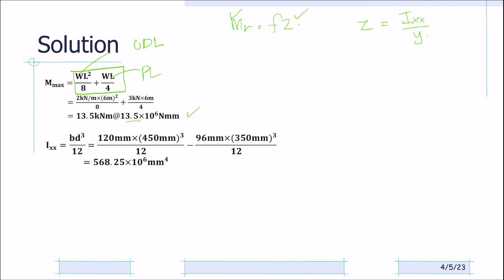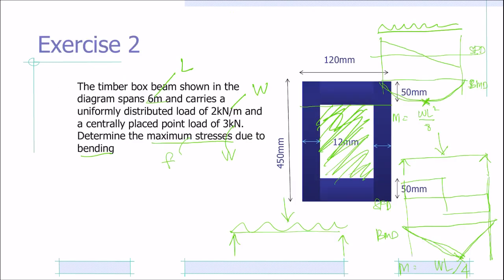So the shape of the beam ada hollow section, so kita akan ambil IXX di luar, yang maksudnya kotak besar, tolak dengan hole yang dekat dalam lah, which is the kotak kecil. Dan kita boleh dapat cara lebih mudah daripada you belajar masa sebelum ni, you bahagikan this is 1, this is 2, this is 3, this is 4. Itu cara lambat lah. Kita boleh ambil this one whole box yang besar, minuskan dengan hole yang dekat dalam. Since it is symmetrical, we can use this cara to get the IXX.